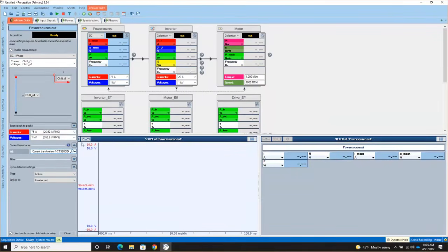Now I need to go up into the span area and select the maximum input range that I expect to use for both my currents and my voltages. All of the power modules built by HBK offer a variety of what we call spans or amplifier ranges. You want to select the span that most closely matches the measurement you expect to make so that you can get the maximum resolution, because the 18 bits of this digitizer will be placed across the measurement span that you select.